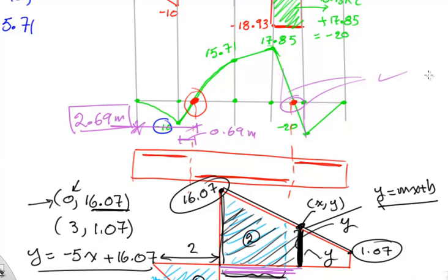And remember, there is another way, which is finding the equation of the moment diagram and setting that equation equal to 0 and then solving for x. So whichever you think is easiest for you, just go for it, and I hope you all got the main idea here. Right? See you in future tutorials.